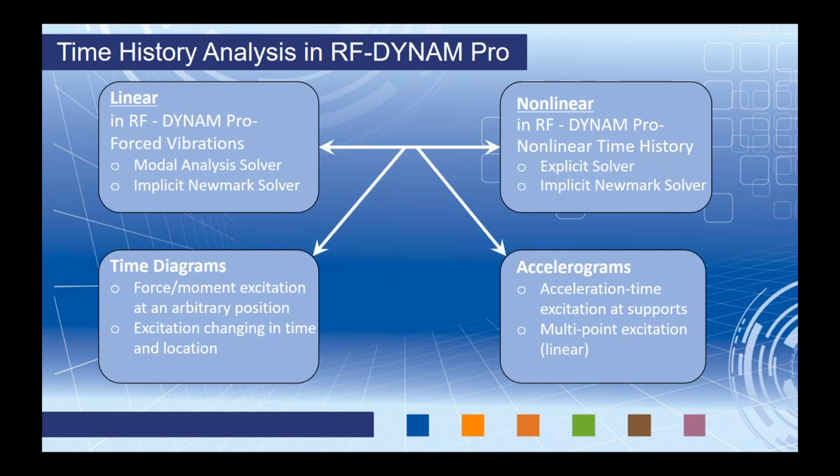Load cases define the location and the excitation of how this load will be applied according to the time diagram. So for example, we would apply loads within these load cases, nodal loads, member loads, surface loads, and many other options to determine where exactly this excitation will take place. The combination of several independent excitations is possible, and the excitation can also vary over time and position.